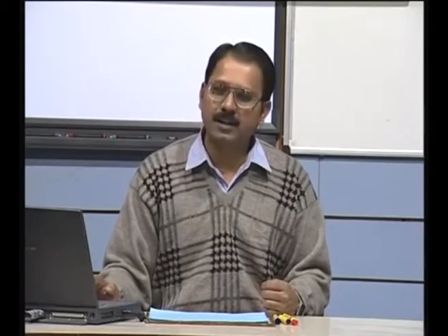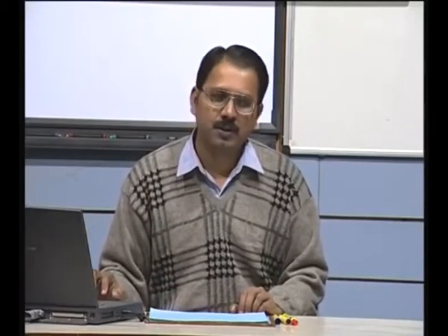Suppose somebody has kept a part model somewhere and I would like to click and rotate it, and I would like to see it from different views. So, I want a three-dimensional geometry in order to interact, then you can go for a VRML. So, what you do as a part of VRML is, suppose I create a part model and I convert it into a VRML format using a translator which is available, and put it on the web and throw it open for others to use and interact.